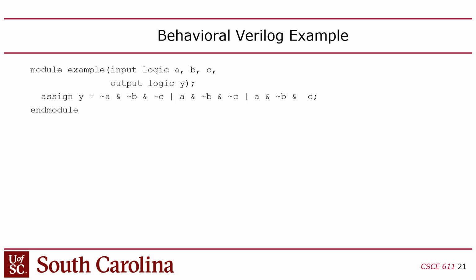So logic can be either a wire or a reg from Verilog. When we taught Verilog, it was really hard to teach when to use a wire and when to use a reg, because it really doesn't make any sense the way it works in Verilog. I was never able to teach that adequately. Most of the class still, by the end of the semester, couldn't figure out when to use a wire or reg. SystemVerilog fixes that. Logic, just use logic. You don't have to worry about it.